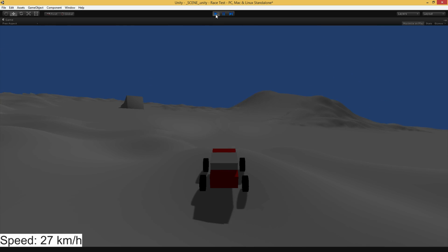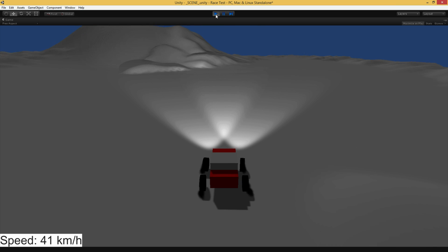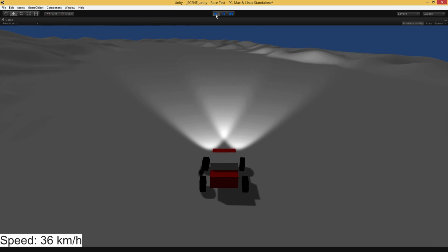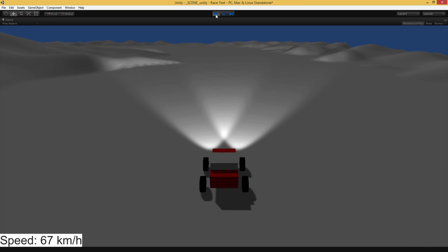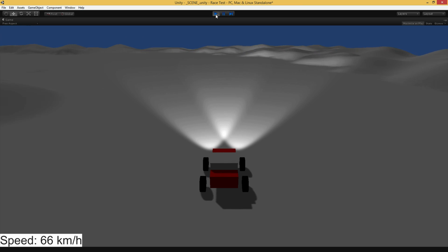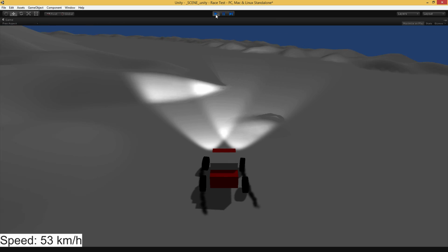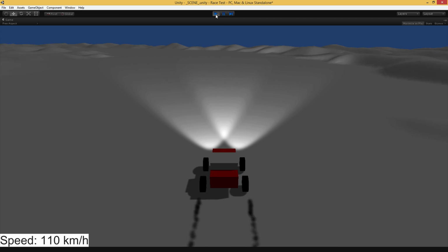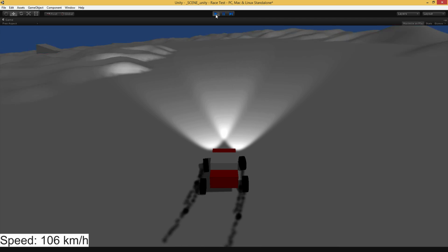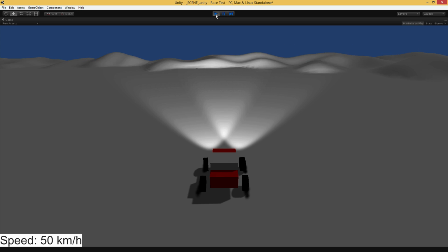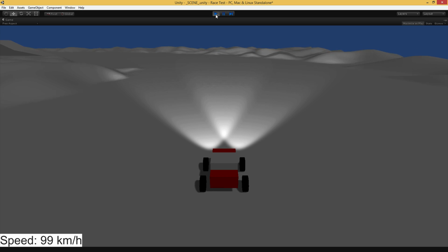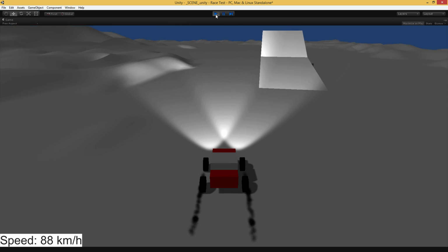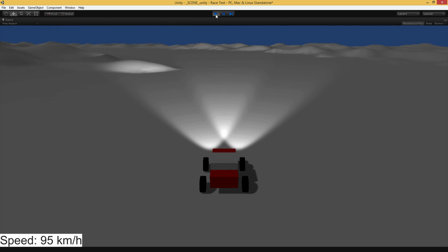And so what happens is, as you go into a corner, as everyone who's ever driven a van or a pickup truck knows, the car sort of tips over some. Well, if your wheels are perfectly sticky, then when you go into one of these sharp corners, there's no give, and the only thing that can happen is your car flips over. What you want to do is reduce the friction, reduce the traction in Unity so that when you go into a corner, there's a little bit of skid. So some of your turning force gets converted into a sideways slipping force instead of having to go right into a roll. But the other thing that really happens, and so that's step number one.